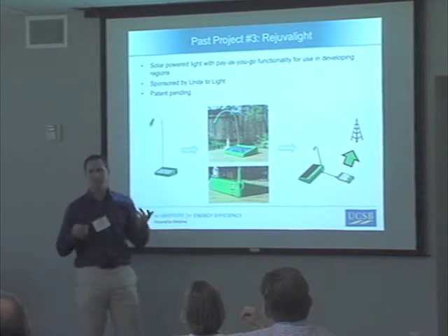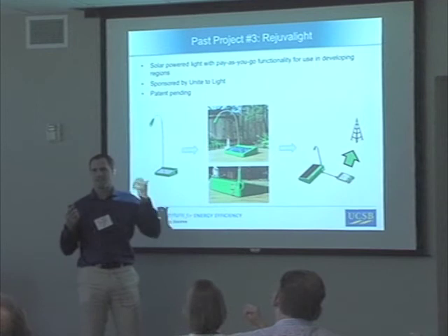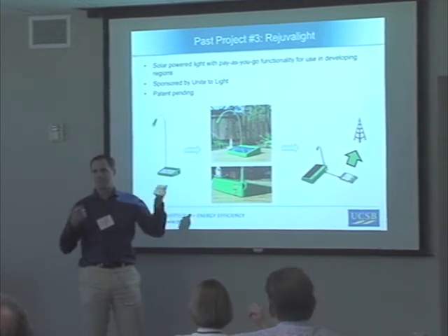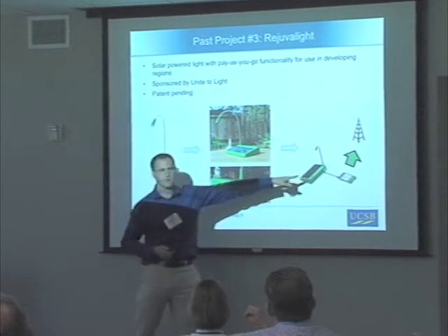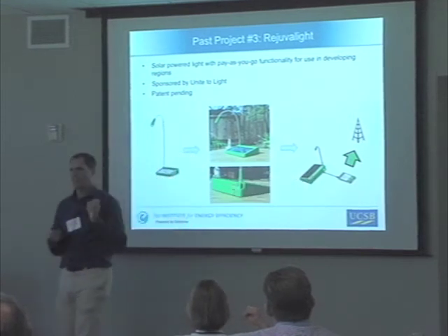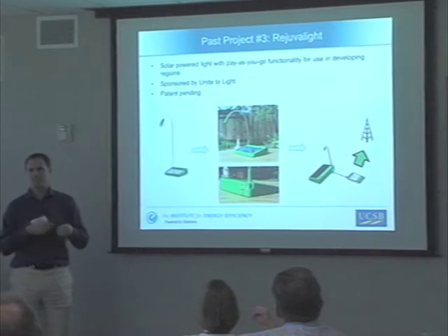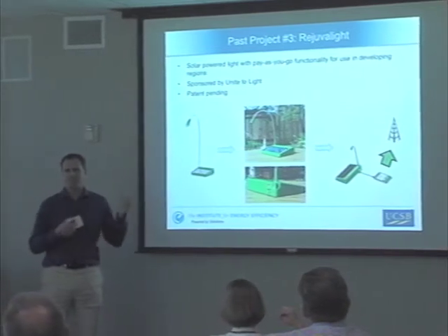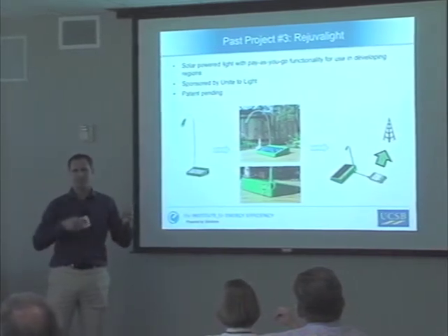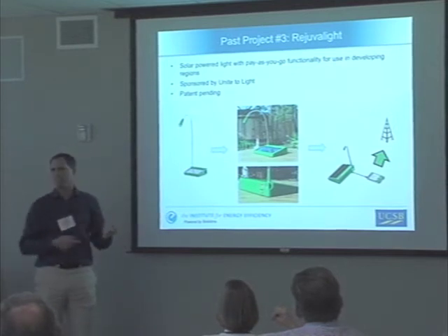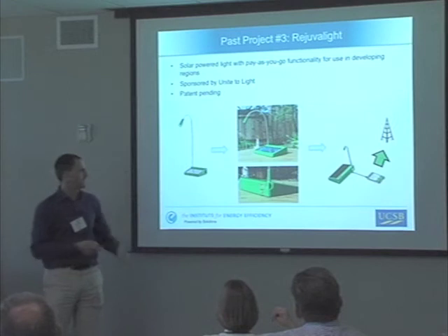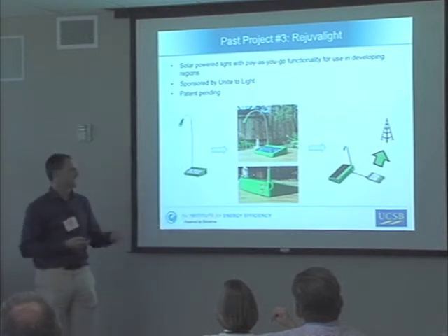And the way they thought to do that was every device has a speaker output, an audio jack. So they would basically run an audio cable into the light and have a circuit. They used a DTMF circuit that can basically detect audio signals and decode a signal that was piped in via audio, and that's how they would enable it.